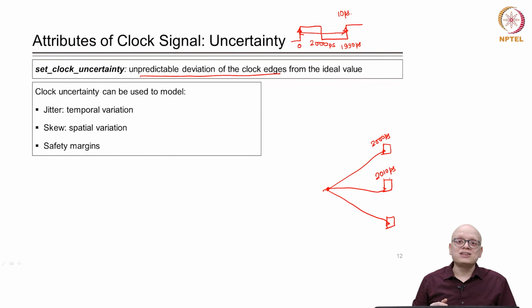In the last lecture, we saw that there can be impact of process induced variations which are not easy to model, and there can be other reasons for which we want to add safety margins in our timing analysis. For example, when we are doing logic synthesis, we don't know the delay of the wires. The wire does not exist, and therefore, the exact wire delay cannot be computed.